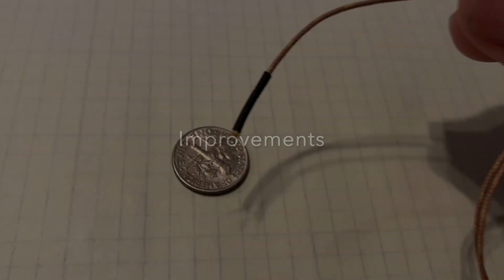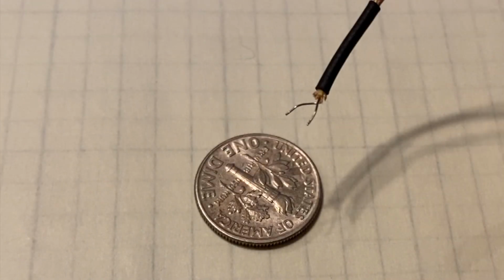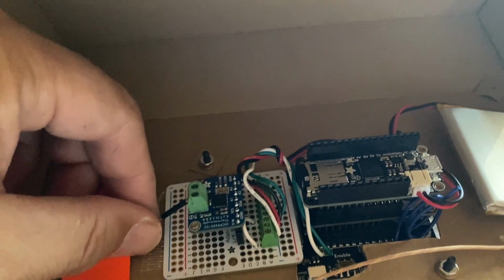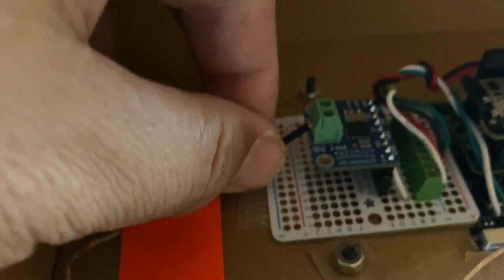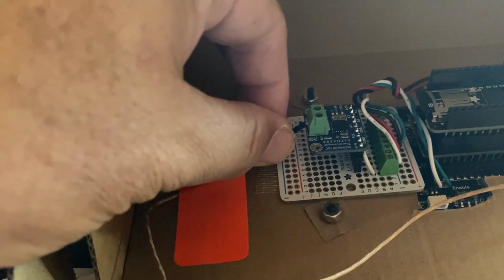Although our first test was successful, subsequent experiments helped us identify some weaknesses in our setup. Specifically, we learned that proper signal processing requires a tight connection between the thermocouple leads and the amplifier. The tiny leads associated with our original thermocouple were not ideal for this. And one of the issues I see with this setup is this little thermocouple has a really slow response time. It just doesn't keep up with rapid temperature fluctuations. And I think it has to do with the fact that the connections in this little terminal block are not really tight, because when I wiggle this around, it responds quite quickly.